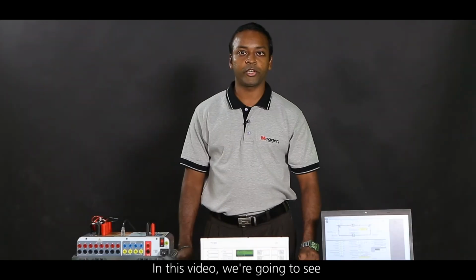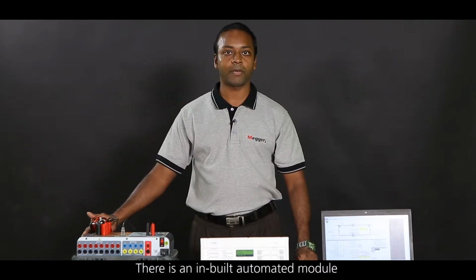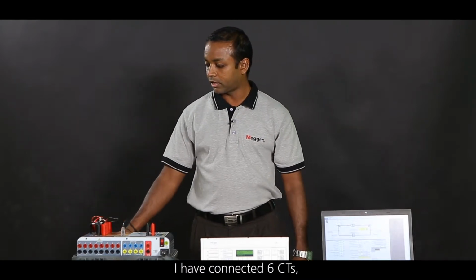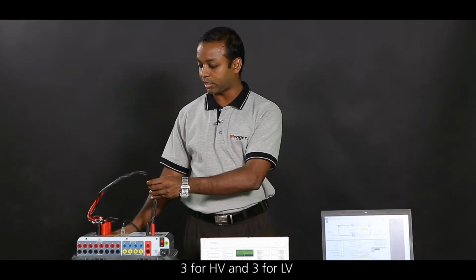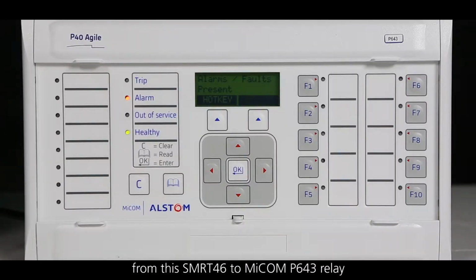In this video, we are going to see how to test a transformer differential relay using the SMRT test kit. There is an inbuilt automated module to test transformer differential relays. I have connected 6 CTs, 3 for HV and 3 for LV, from this SMRT46 to a MICOM P643 relay.